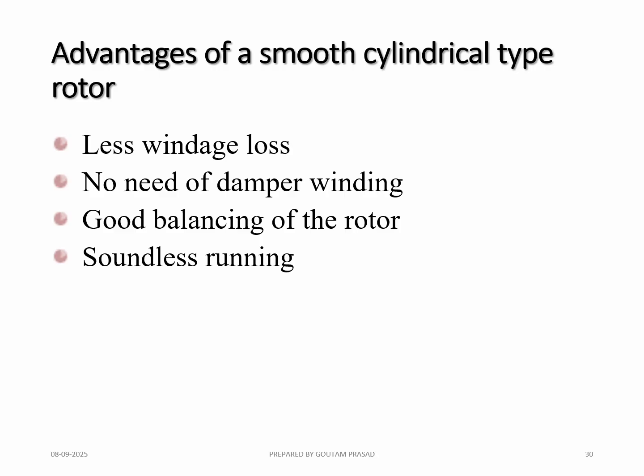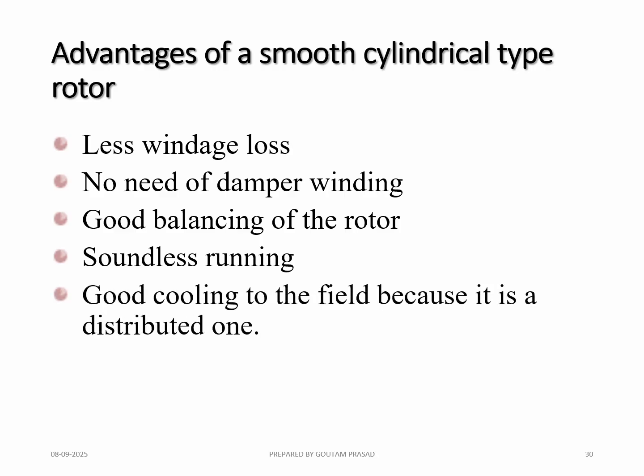Soundless running. So this type of cylindrical pole rotor is soundless in nature. Good cooling to the field because it is distributed. So this DC winding on the rotor is distributed on the periphery of the rotor. So cooling is better as compared to the salient pole rotor.